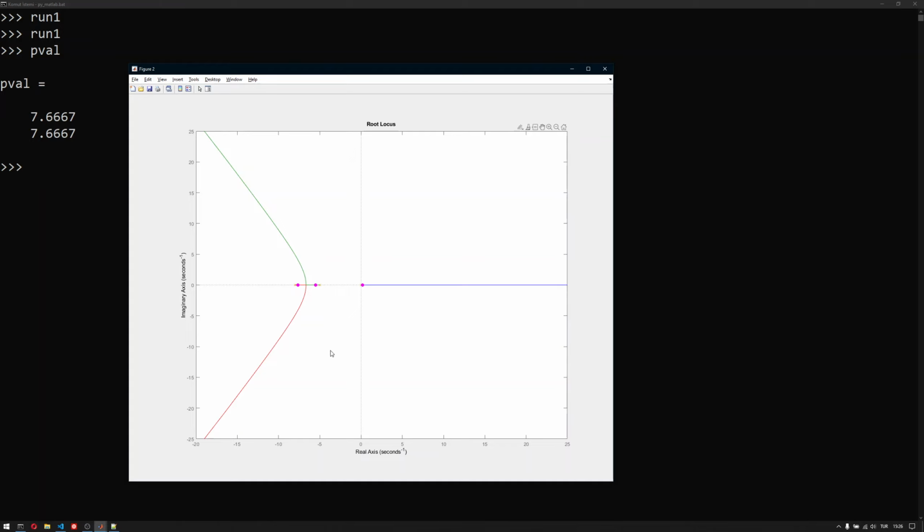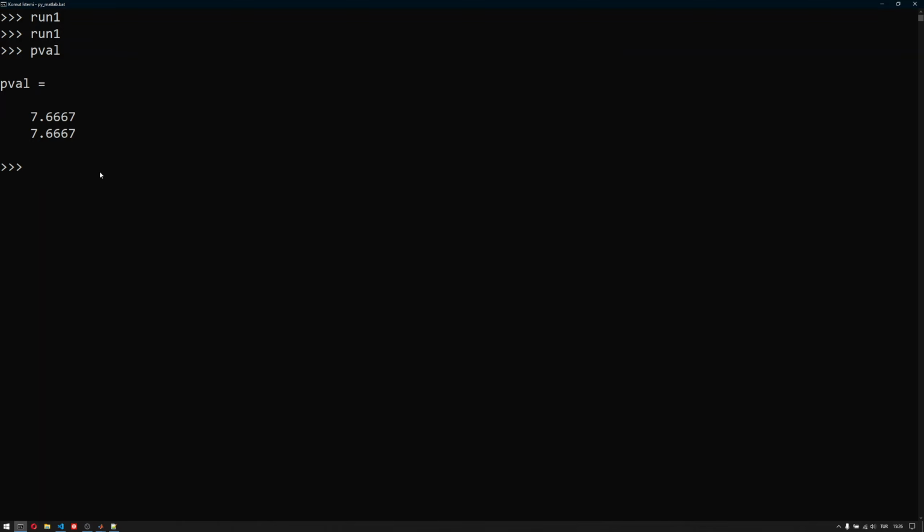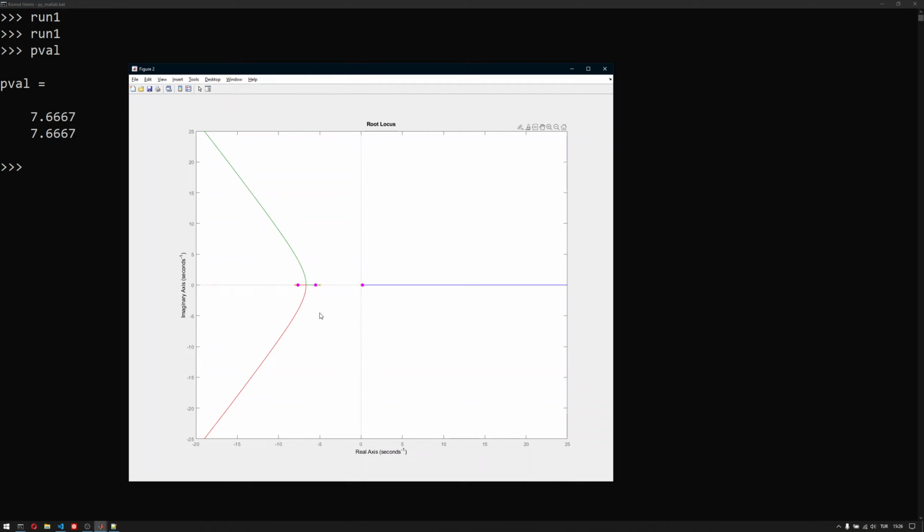We don't have an underdamped solution, and therefore there is no real value of the complex pair. And 4 divided by the real value of the complex pair, which is zeta times omega n, is not really usable here. We are looking for a complex pair, and it should be on a certain line, on the settling time line exactly, but it's not happening.